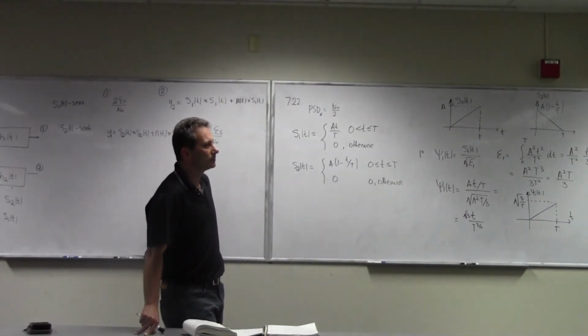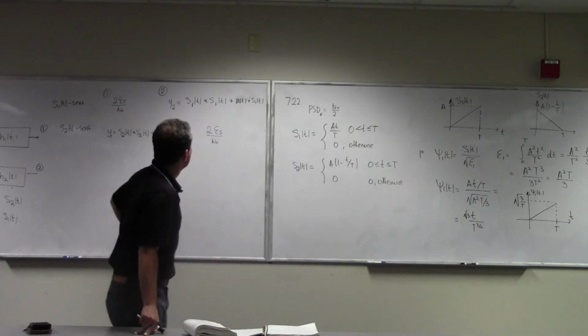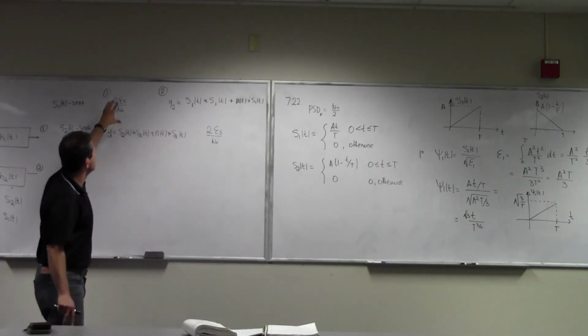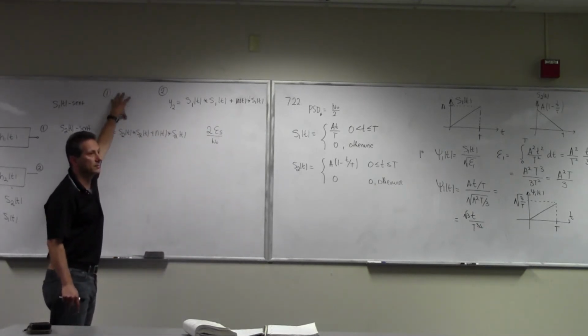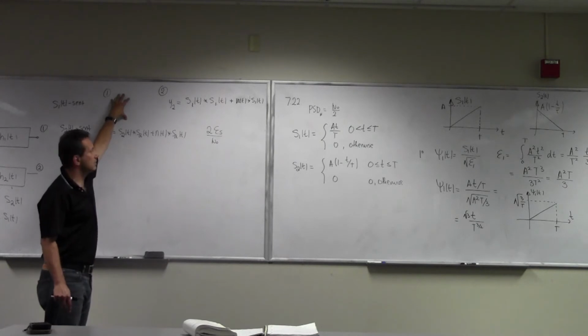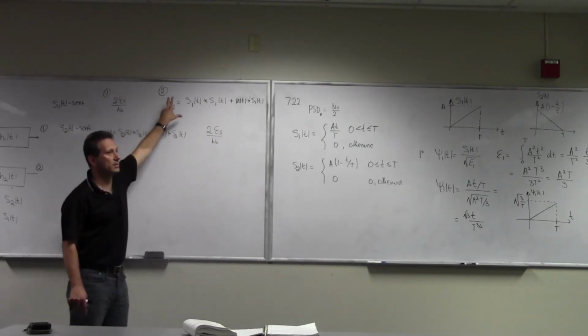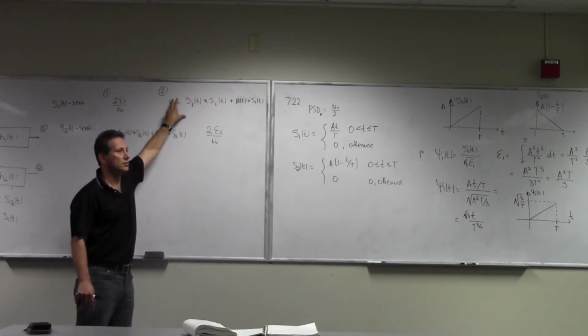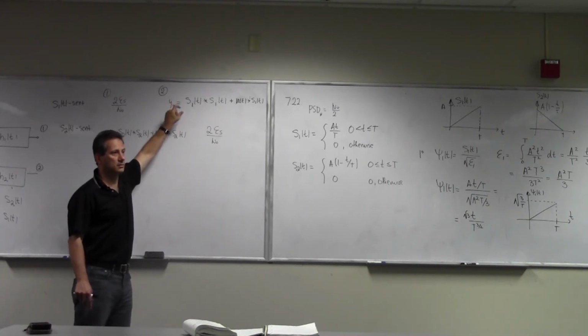Because when we did the proofs during the lecture, we ended up with the matched filter as being the optimal. Correct. The optimal for maximizing signal to noise ratio in the branch. But the question is, what happens in the other branch? If they're not orthogonal, you may get a substantial value there.